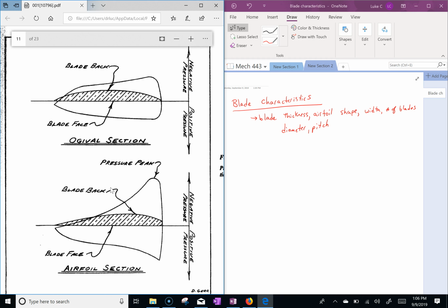You see these huge spikes in these airfoil shapes, but you don't see them too much in this one. They'd rather go with this, because it won't cause cavitation as frequently, where you drop your pressure too much. It's going to cavitate the water, and then you have many explosions that could hurt the prop over time. So that's why we go with this other shape for prop designs.